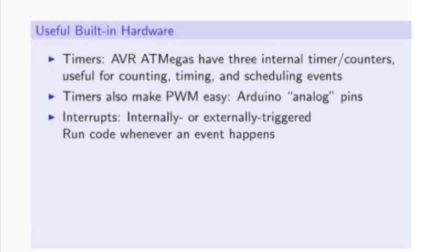So what this is great for doing is monitoring things. If you need to monitor the serial line, you set an interrupt to flag when new data comes over serial. If you need to monitor the input pins for button presses, you do the same thing, and as soon as the button's pressed, the CPU puts down what it's doing, flips over to the interrupt service routine, runs it, and then picks up again where it left off. So these are fantastic. Instead of waiting and looking to see if something happens, using interrupts, you can fire code as soon as whatever that is happens.